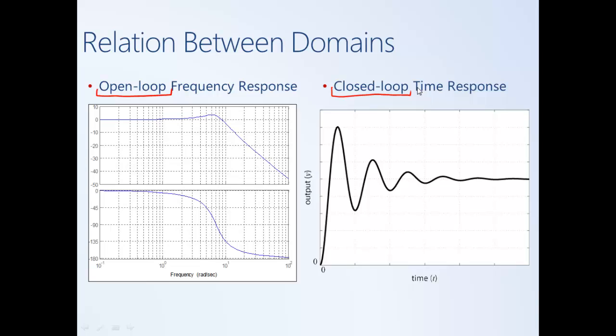So first, let's just try and use our intuition of frequency response to connect the two, and then this will be summarized on the subsequent slide. So let's first think about steady state error. For a type 0 system and step reference, E steady state depends on the DC gain, and it has some sort of form like this.